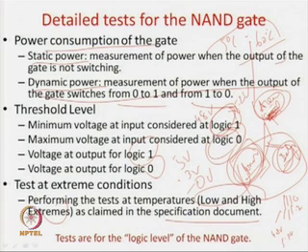So, if it is temperature, you have to do all the operations at such a high temperature, and also if there is some specification like it can work at so much pressure of mercury and so forth. All the tests we have done have to be verified at these extreme test conditions, and only then can we say that your NAND gate is satisfying all the conditions required in the specification document, and that it will operate functionally correctly with all the test parameters like power consumption, threshold, delay, etc., within so and so degrees of temperature and so much pressure.